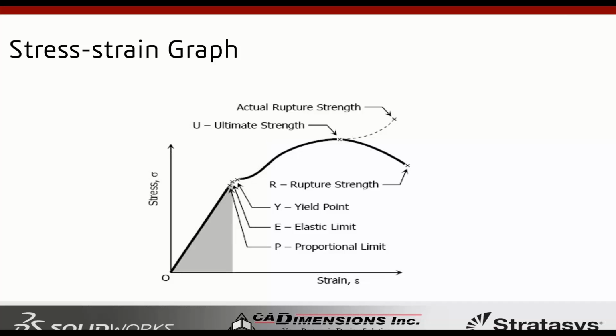What happens is there's some form of linearization going on, where SolidWorks simulation is trying to create a curve as close as possible to those material properties you're putting in, but it's not really precise. As I had mentioned, it's linear.